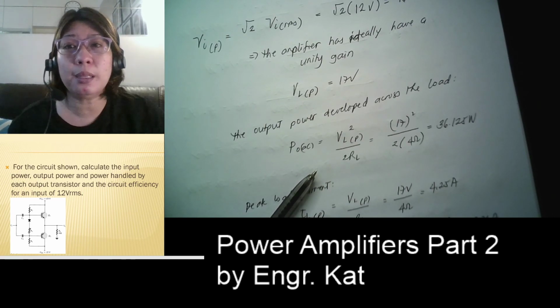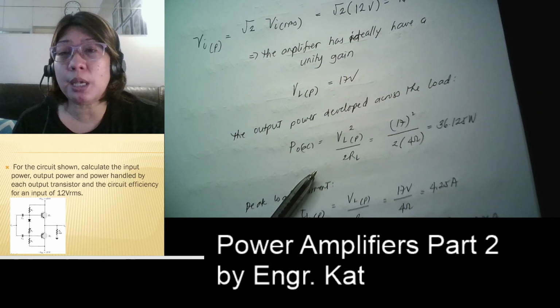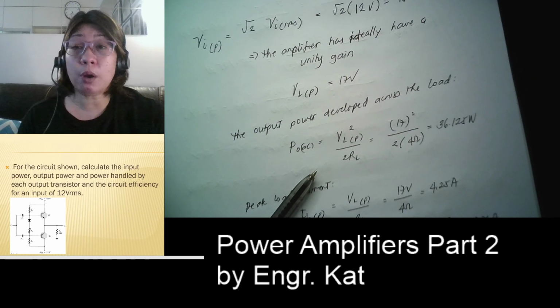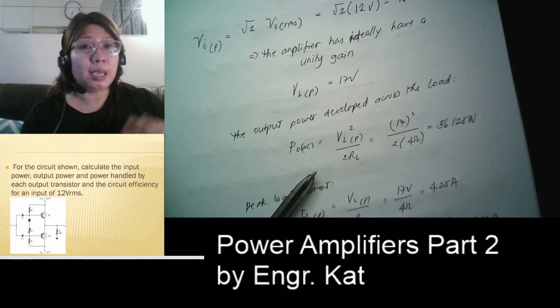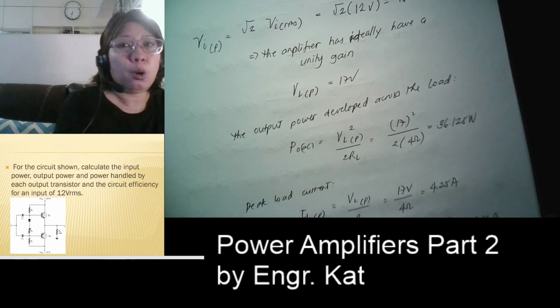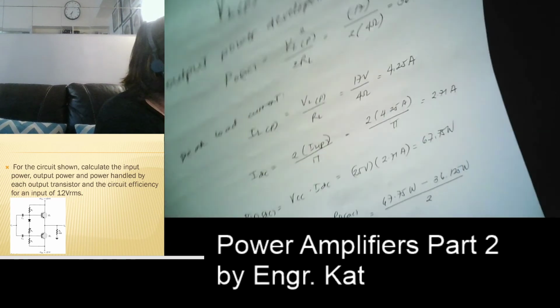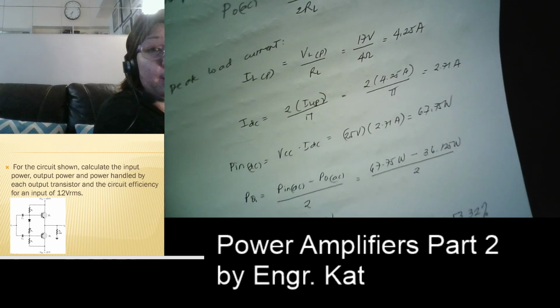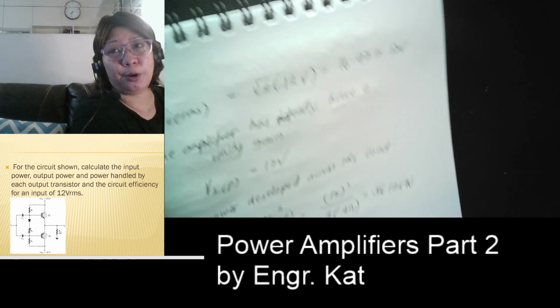We cannot do this in class A, because in class A, even though we use transformer coupled, the maximum is 50%, and that 50% is theoretical, so it can never have an efficiency equivalent to 53.32%. This 53.32% is possible for a class B amplifier.